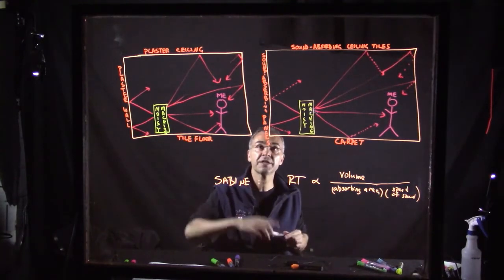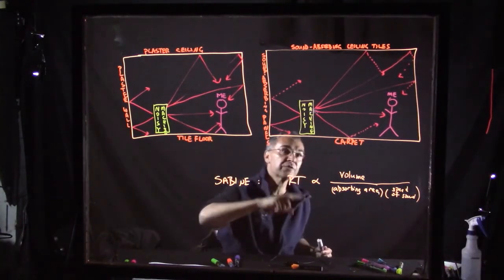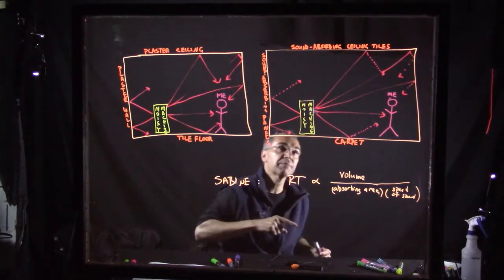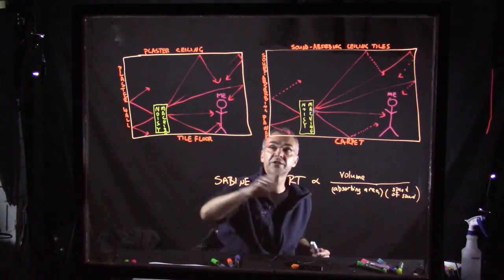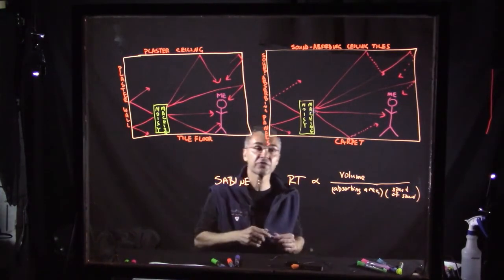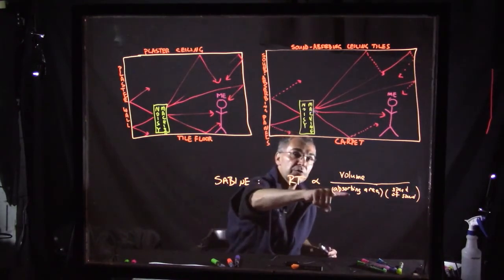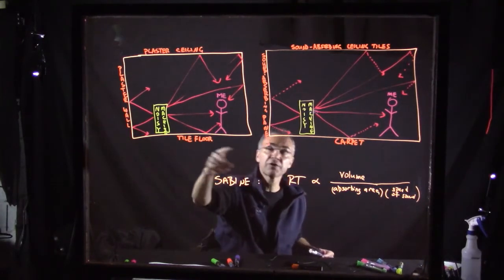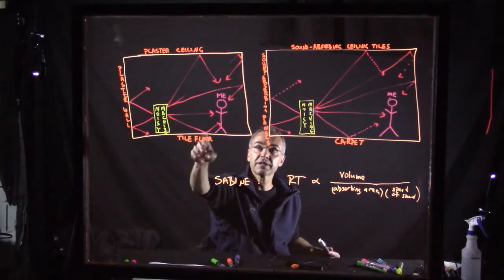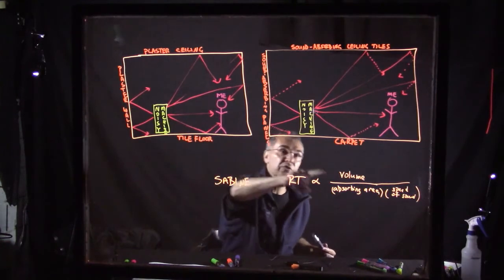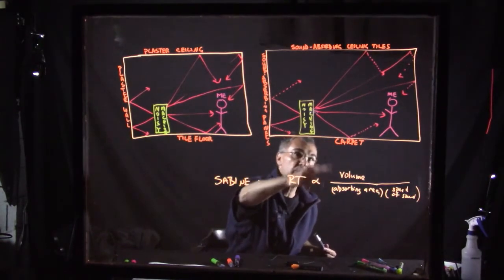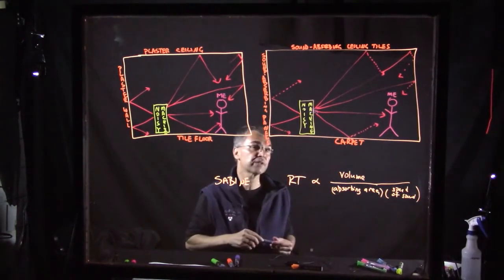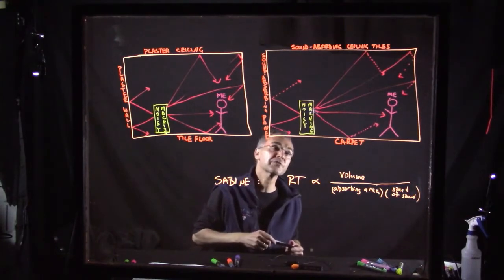And then meanwhile, every time the sound bounces, it gets attenuated if it bounces from a surface which is treated. If it bounces from a hard surface, it doesn't get attenuated. So you can see it makes sense that the reverberation time is longer. The sound lasts for longer in the room if it bounces off of hard surfaces. The sound decays away more quickly if it bounces off of these attenuating soft treated surfaces.